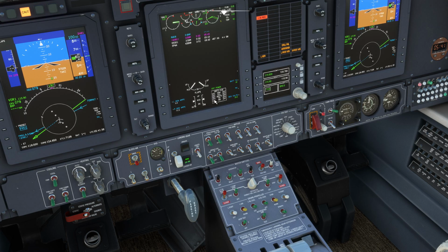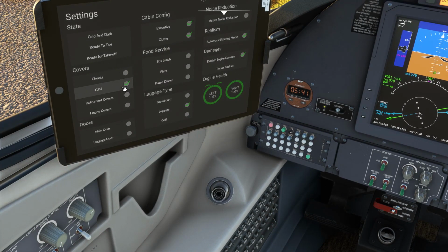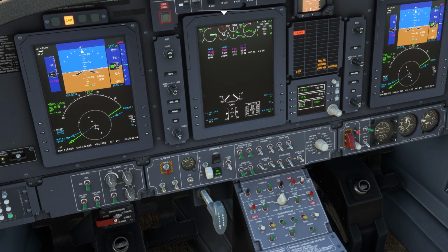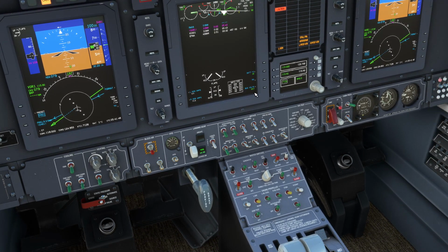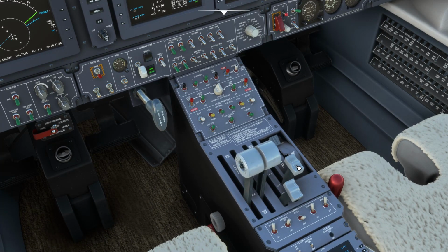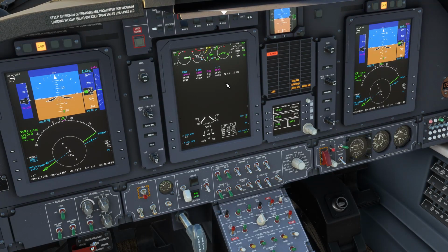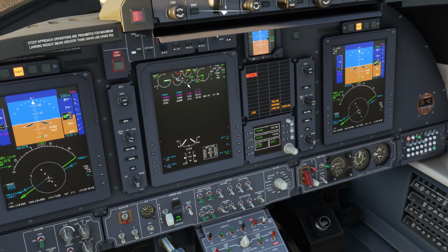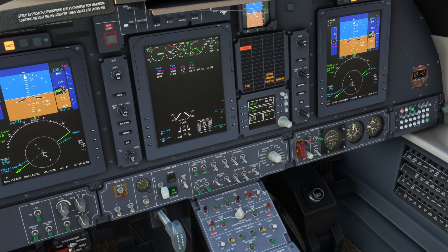And now we disconnect our external power. Bye bye. And our aircraft is powered through the engine, so that is not changing. Remaining engine: for that, our condition lever goes to flight idle. We need more power provided by the right engine in order to start the left one. And again, so we are stable here.